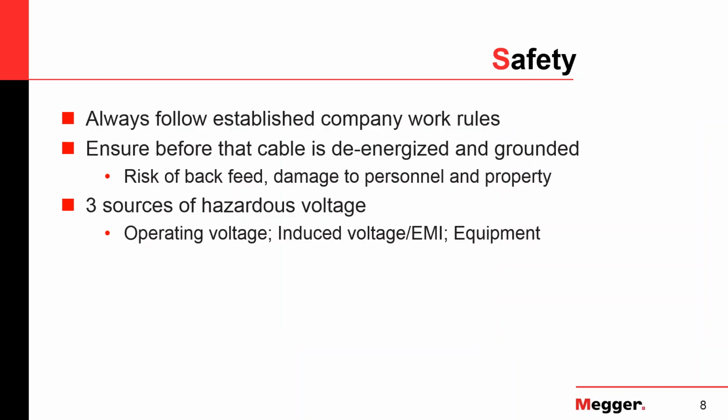Very important always is safety. Always work as safely as possible. Your company probably has rules, and you always have to comply with those rules. But typically, in cable fault location, you work on a de-energized cable that is to be properly grounded. And there are always sources that can endanger personnel that is working around a cable fault.